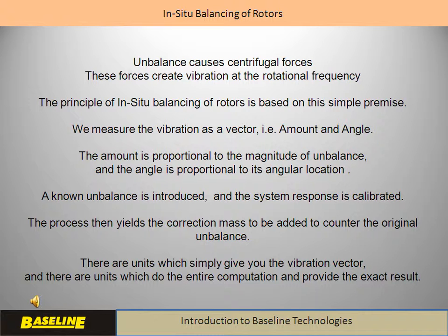Field balancing or in situ balancing is the process of balancing the rotor by running it in its native assembly with its own power. There are some field balancing instruments which simply give the vibration vector, and there are other instruments which do the entire computation and provide the exact result of where and how much mass is to be added to balance a rotor.